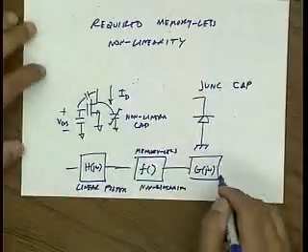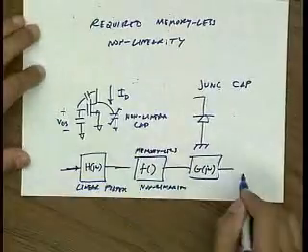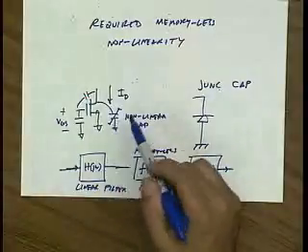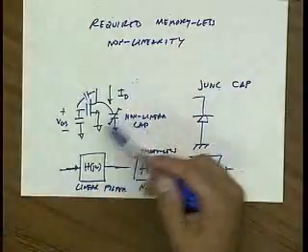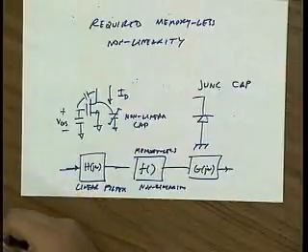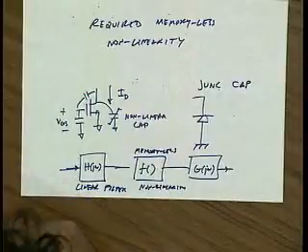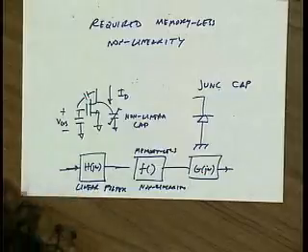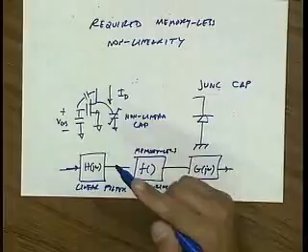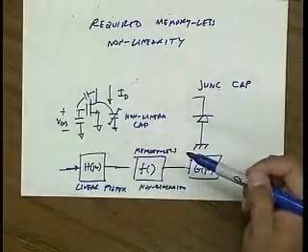Okay. So it seems like the techniques that we've developed, if we ignore this nonlinear capacitor, can still be applied to even a circuit that has frequency dependence. And in particular, if you're careful, you can just do this by inspection. So for instance, if you have a tuned amplifier, then you know which distortion products are going to get filtered and which ones are not.